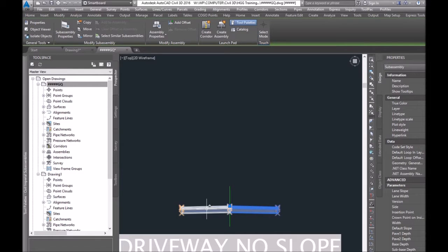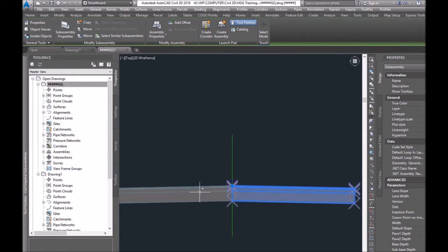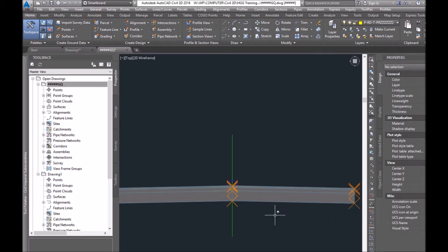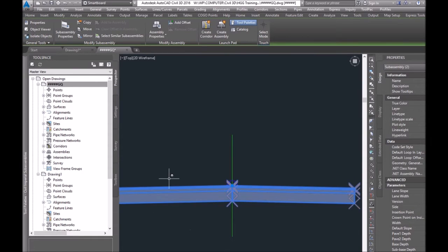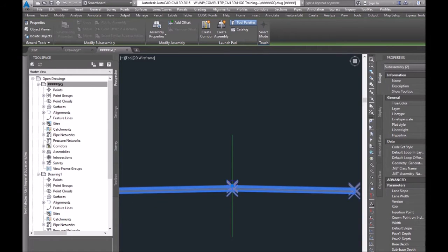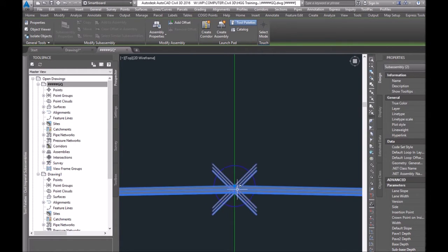In our case, we just have a standard paving section with nothing on the side. So what I usually do, just to give myself options in case someone wants a subgrade analysis, I give it different paving depths. So you can specify subgrade here. You can see that it's updating right in there. But let's say it's 5 on 4.